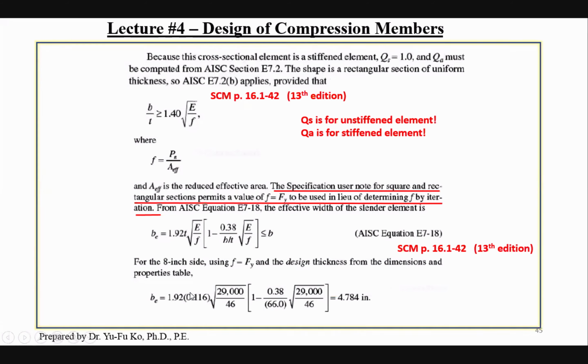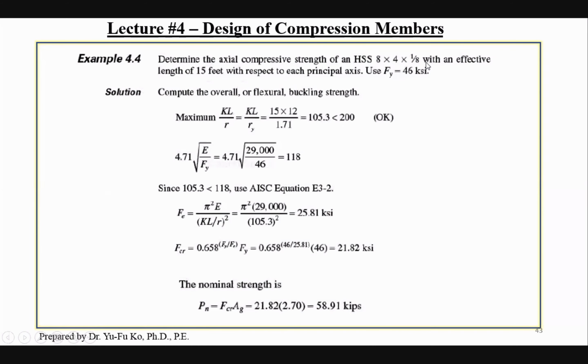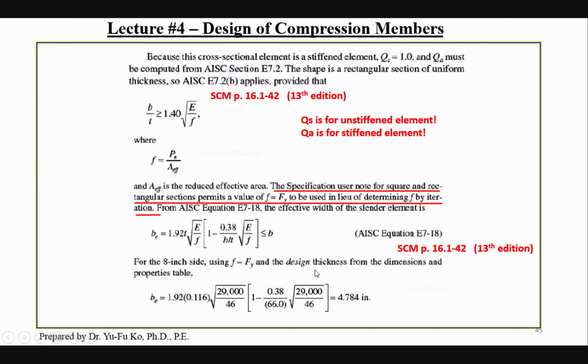How did you get the 11.6? Is 1/8 here times 0.93. So 0.93 is the constant. It's a specification constant, the so-called design thickness. You do a little bit of reduction for the nominal thickness. You call it design thickness. That's by definition out of the code. Is that to be conservative? Yeah, it's conservative. That's correct.